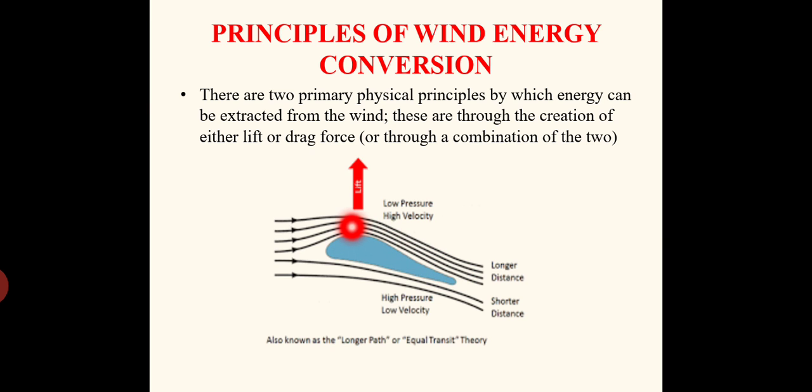We know that if one form of energy is increased, here kinetic energy is increased, in the upper portion the velocity has to be increased due to the flow contour or the higher distance to be covered. Velocity increasing means kinetic energy is increasing. So the only option is to reduce some other form of energy, that is pressure energy.